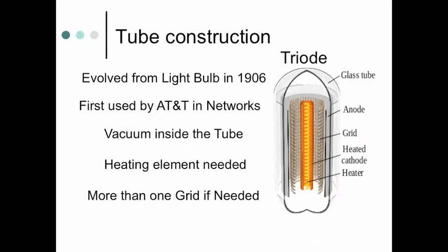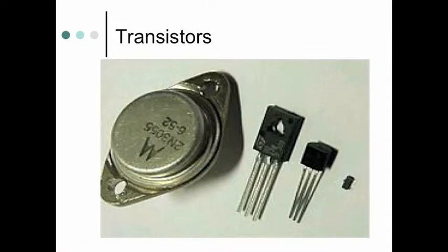Now, this was started in 1906 is when they started with tubes. But transistors look like this. The one on the left, the 2N3055, is a power transistor. And then these are other transistors, and they get pretty hot. So the metal casing here has two bolt spots on it, and it's usually bolted to a big piece of metal with fins on it so that air can cool it. It's called a heat sink. So it takes the heat that's generated inside of this little device and it sort of radiates it so it doesn't overheat and blow up.